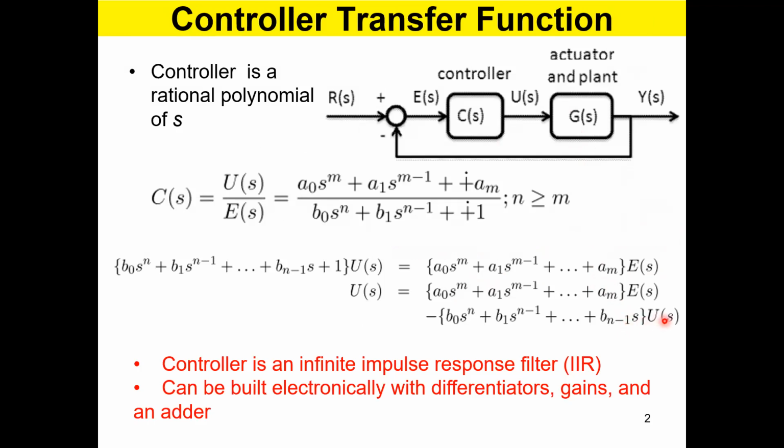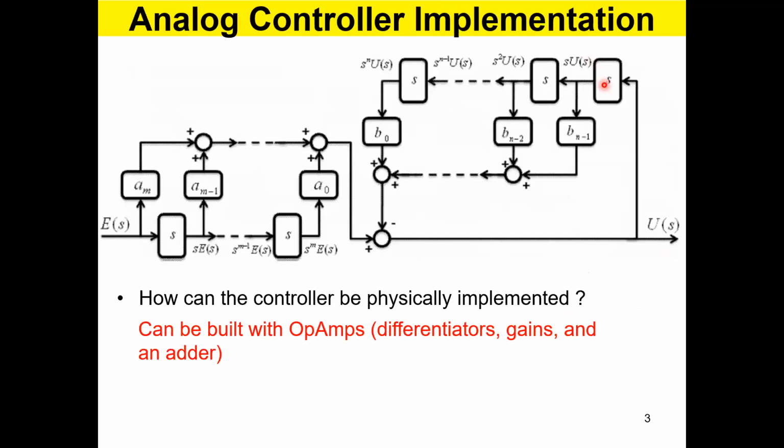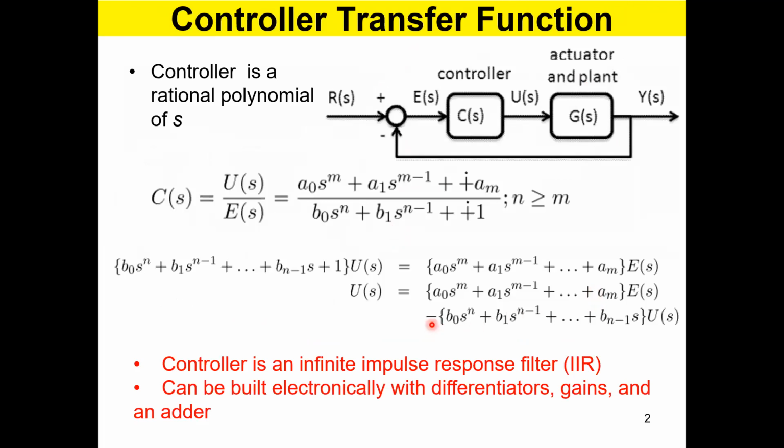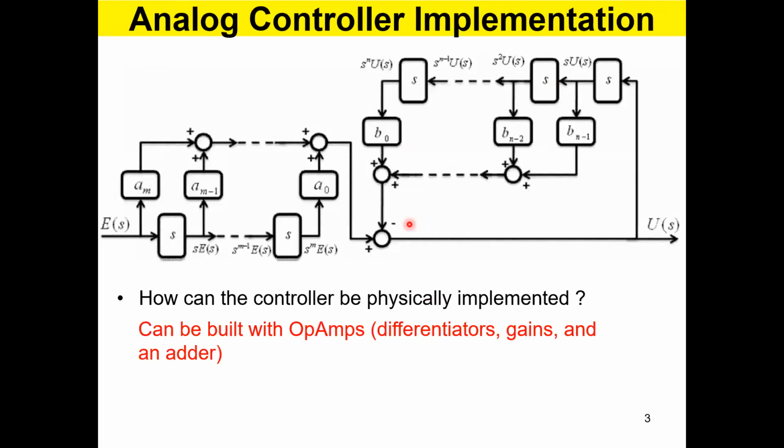the control signal gets differentiated and multiplied, differentiated, multiplied. So it happens like the differentiation. So this is the differentiation channel, successive differentiation, and every step, you multiply it with a gain and add together. So when you add all of these terms here, you bring it to the summing point as negative because of this negative sign. Okay? So the result is actually the control signal.